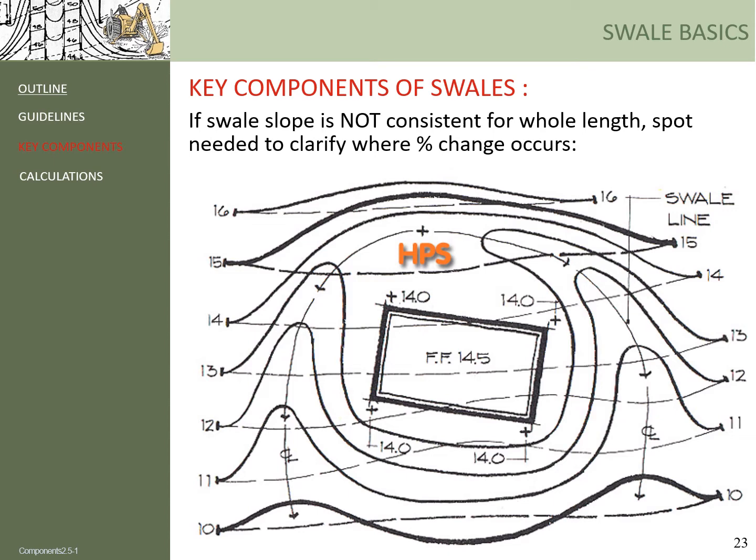In this example instead, you can see that there appears to be a change in spacing along the center line of the right slope. The green spacing seems to be longer than the other two, right? This indicates that there is a slope change somewhere along that center line, and you must indicate clearly where that slope change occurs using a spot elevation, like this one.